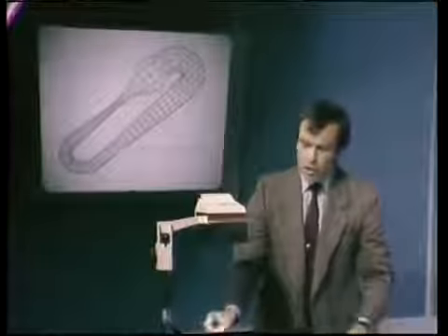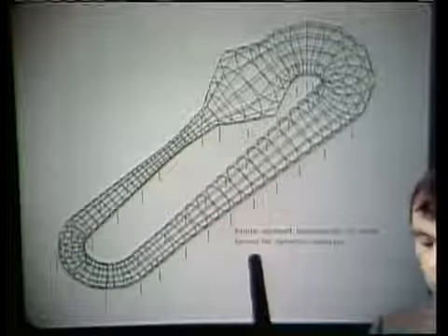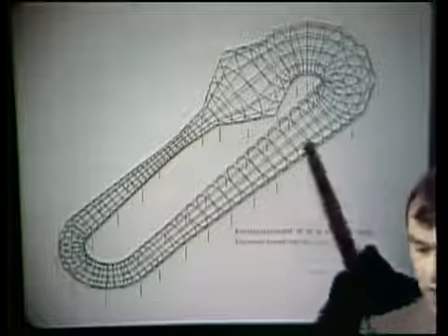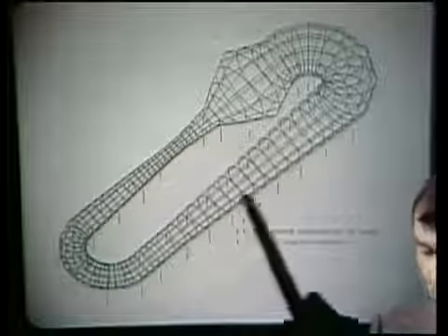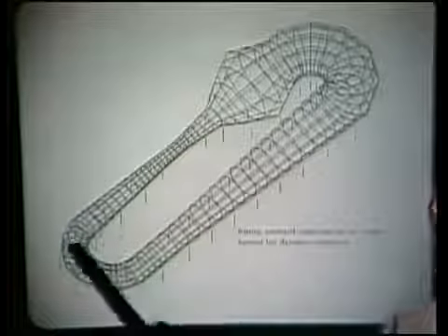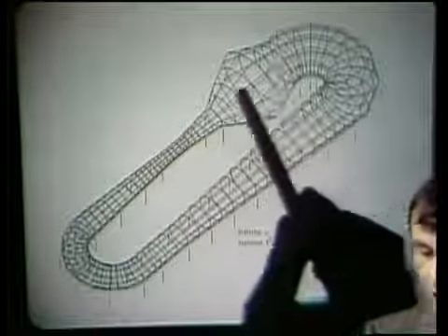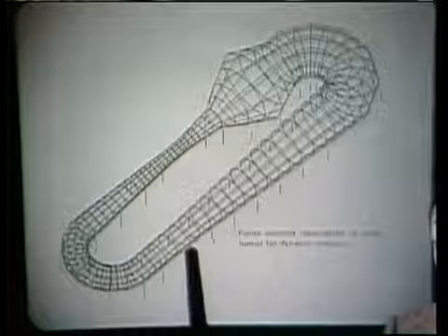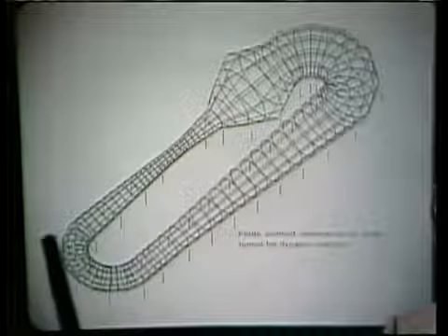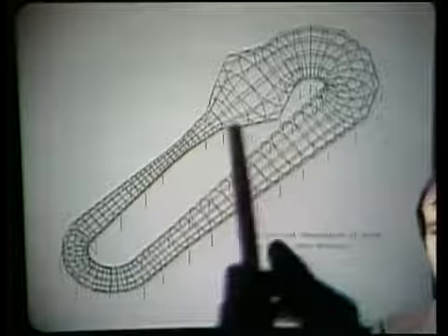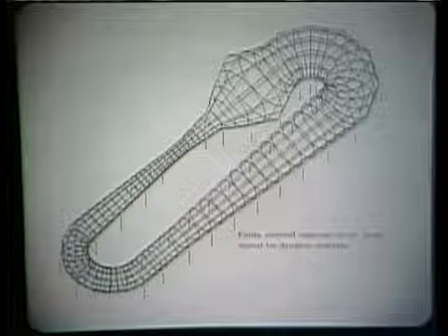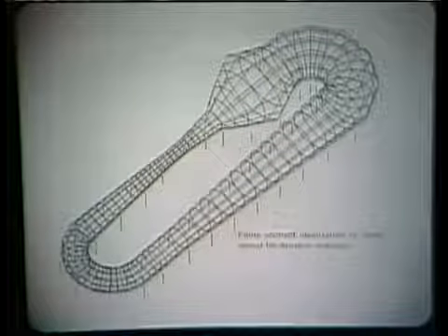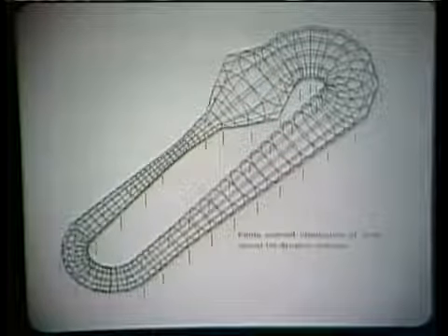Finally, here you see the finite element idealization of a wind tunnel that was used for the dynamic analysis of this tunnel. You can see a large number of shell elements were employed in the idealization of the shell of the tunnel. Then, of course, supports were provided here for that shell. This was a very large system that was solved, and the eigenvalues of this system were calculated using the subspace iteration method that we will also be talking about in this set of lectures.